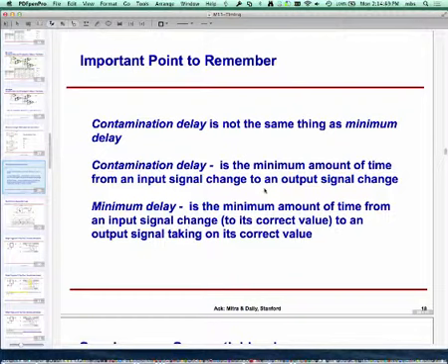So let's go back to our timing stuff that we were doing. Last time around, we started on this timing issue and I described that for combinational logic, there are two timing parameters which are of interest. One is the so-called propagation delay, which says what is the latest time from when the input stabilizes to when the output becomes stable. And the other one was contamination delay. Contamination delay says, from the first time that the input changed, what is the earliest time the output changes. And we'll see the role they end up playing in a short while, but these are the two.